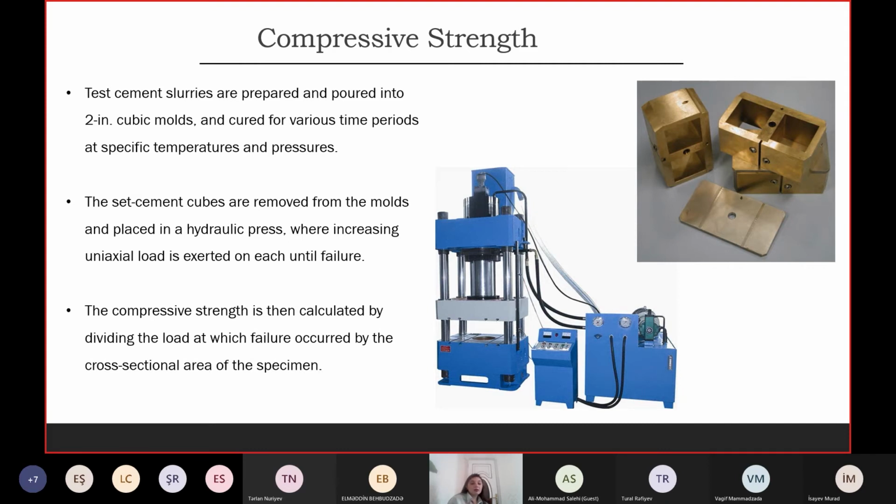And the strength of cement, how solid, how strong is this? How can it withstand the formation fluids, how resistive is it to any change in the well? How is it providing isolation for us? And for this one, we always want to get quicker compressive strength development. We have a few ways to measure compressive strength, and a very old version is still used, but it is used as an alternative.